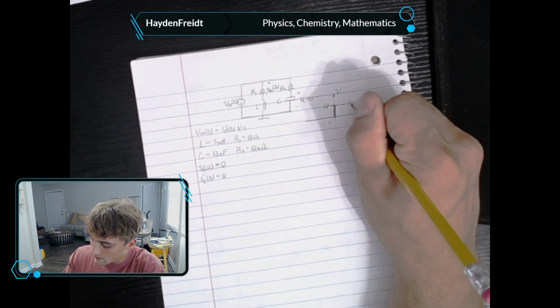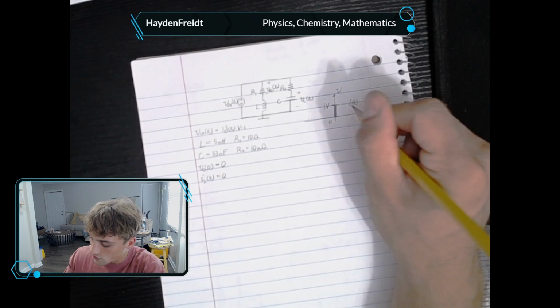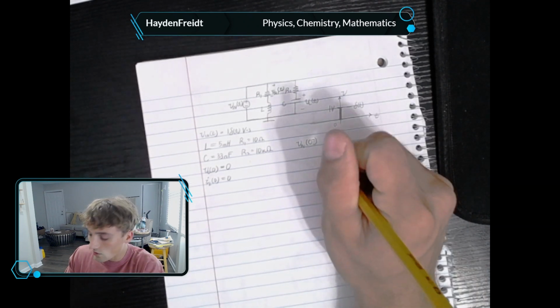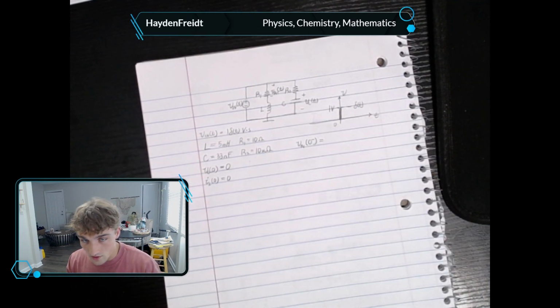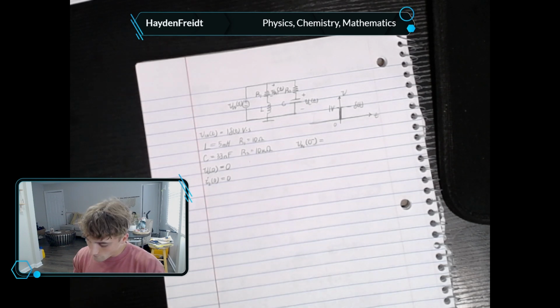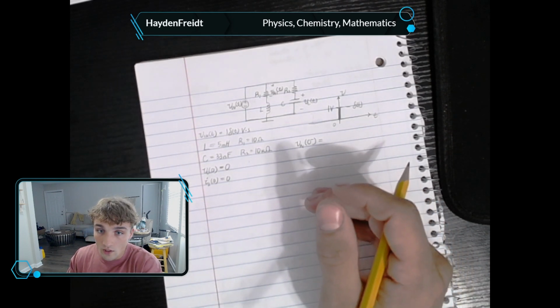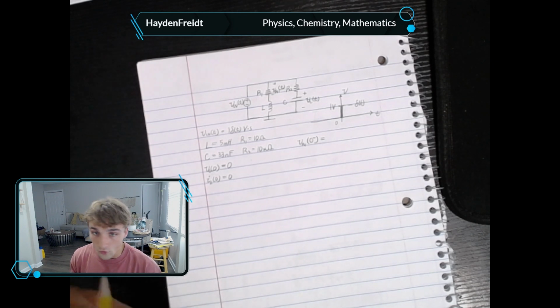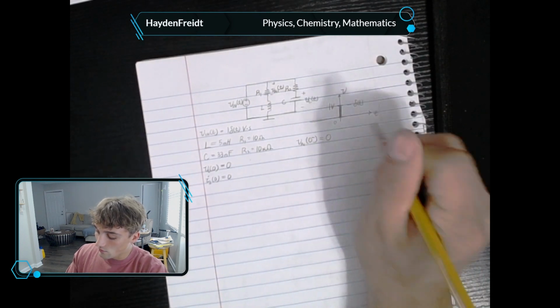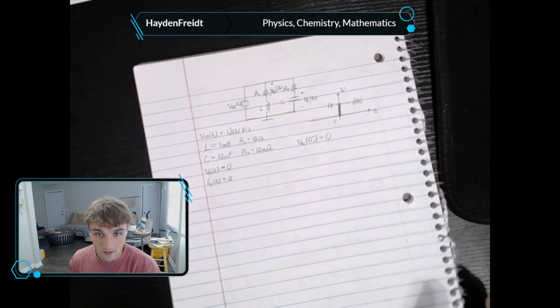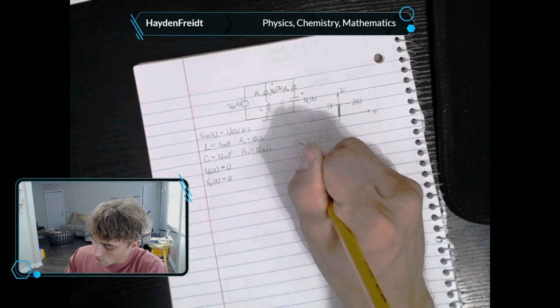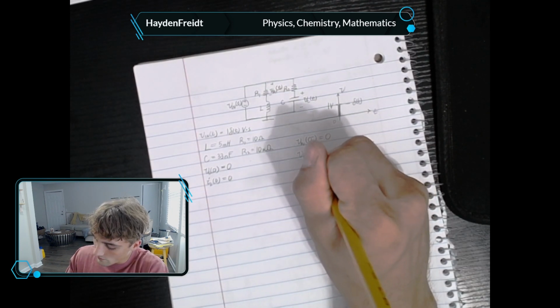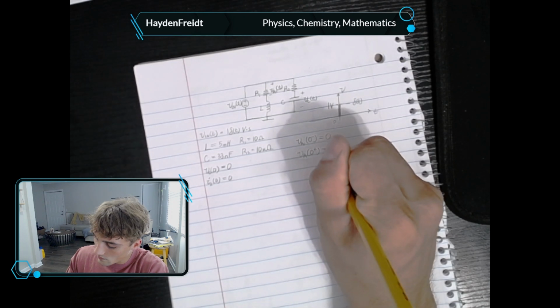I'm trying just to give some insight that this is the impulse function. The 0 with a negative means just the instant before t equals 0. If it were a positive, it'd be the instant after t equals 0. So just moments before t equals 0, we have no input into the circuit. There's no voltage. Therefore, there's no current. Therefore, the voltage across R1 is just going to be 0. The impulse hasn't occurred yet, just moments before.